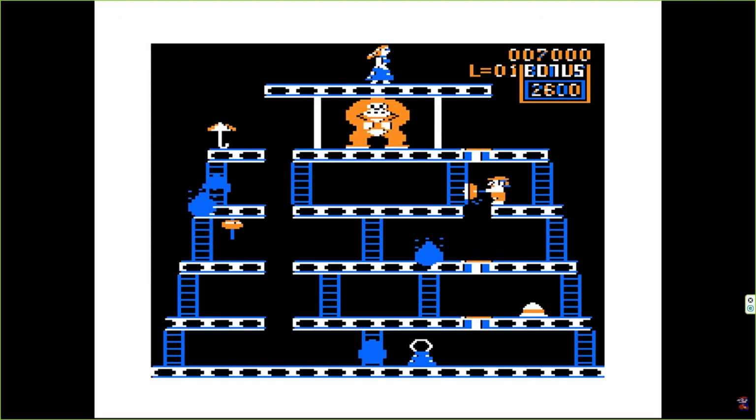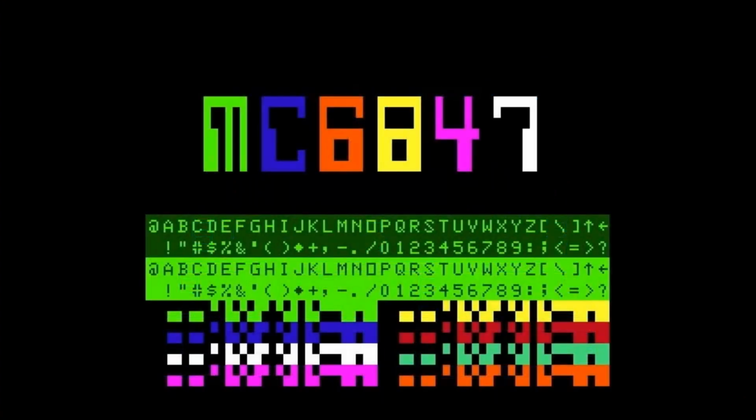To select the right color for the displayed pixel, I use the same multiplexing trick to choose between the possible palette options. Thankfully, the first 8 colors are consistently numbered, but then you have black. Actually, there are 3 different blacks, and they are all indicated as the absence of a color rather than being a color. I've said it before, and no doubt I will say it again. The 6847 has some interesting behaviors and limitations.